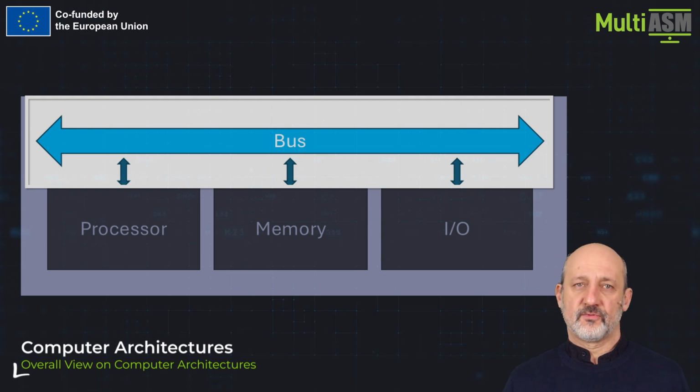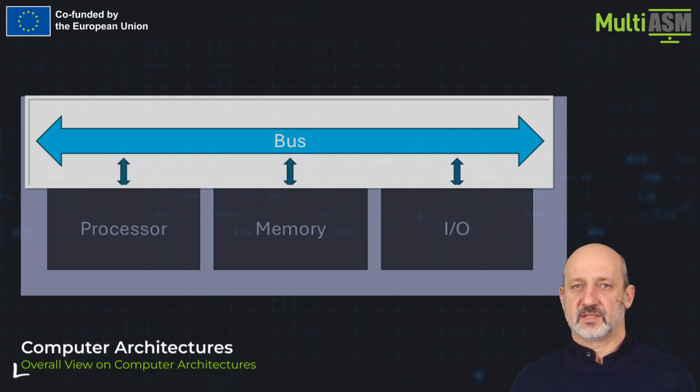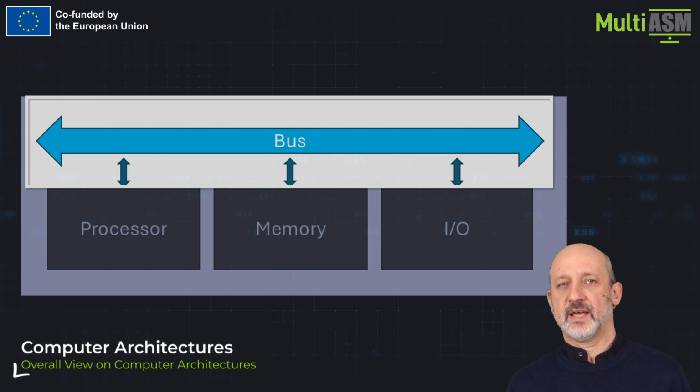The control bus is formed by lines of different purposes, mainly used to synchronize the elements of the computer. In its minimal implementation, it includes the read and write lines. Read line is the signal sent to other elements that the processor wants to read the data from the unit. In such a situation, an element, for example memory, puts the data from the address cell on the data bus. An active write signal informs the element that the data which is present on the data bus should be stored